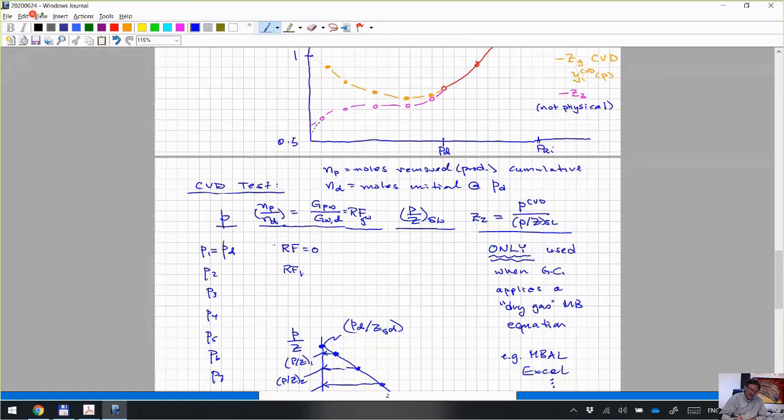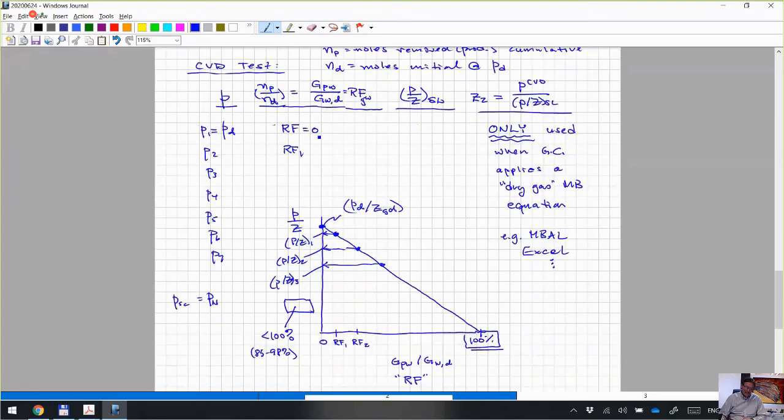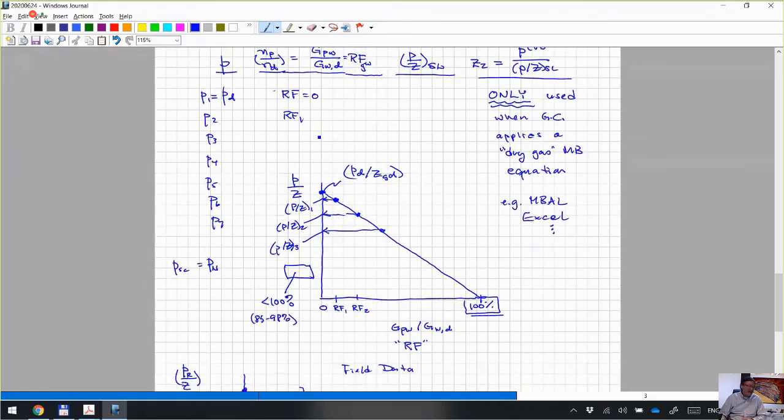It actually goes down towards infinity. I mean, I'm not even sure. I've never taken from the PVT package and calculated the two-phase Z factor. If you deplete the CVD and the EOS model down to very low pressures, 1 atmosphere, it's going to go towards 0. Okay, so that's everything I wanted to cover, unless you have questions on how to correct gas material balance.